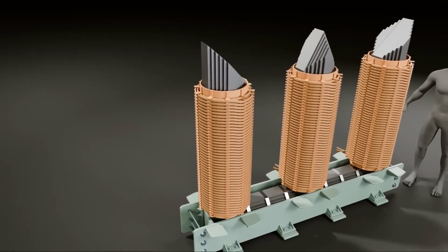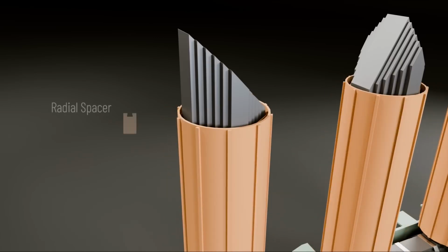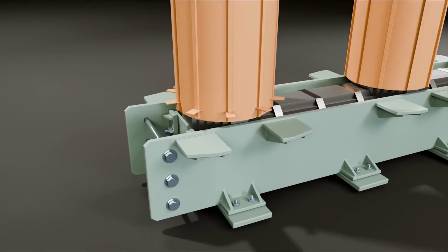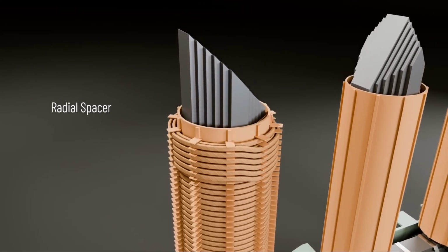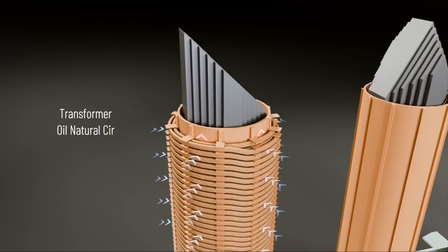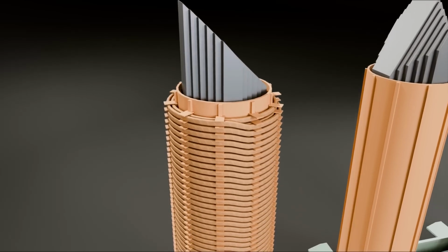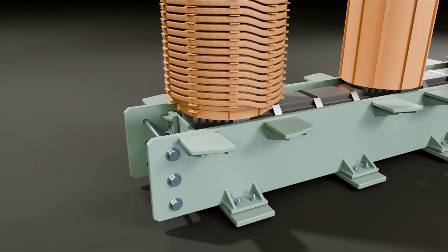The winding arrangement of a power transformer also includes axial and radial spacers. Axial and radial spacers are typically made from insulating materials like pressboard, epoxy resin, or other high-strength insulating composites. They prevent winding deformation under mechanical stress, ensuring long-term reliability and performance. These spacers provide proper gaps or ducts between different conductors, allowing transformer oil to flow and cool the windings. Additionally, axial and radial spacers ensure proper insulation and structural integrity.